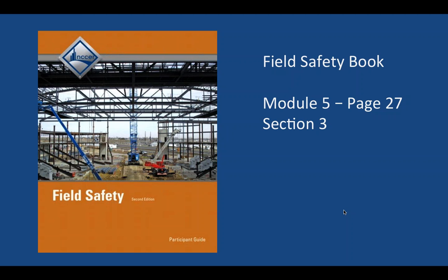Okay, so first of all, who can operate and who can be on an aerial lift? Only people that are trained, only employees that are trained, and employees that are authorized, okay? Now, I want to bring something to your attention. If you recall, when we talked about the 3 different classifications or types of scaffolds, aerial lift is one, okay? So remember that a pole scaffold, like a wood scaffold or a tube and coupler scaffold, something coming from the ground up, would be a supported scaffold.